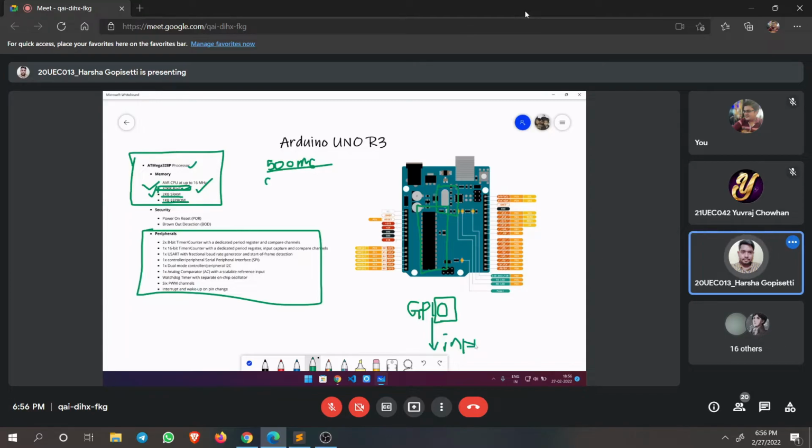You saw the input case in the sonar project, no? There you will be taking the duration. Actually, pulseIn will keep the echo pin high. Whenever the trigger signal comes to the sensor, it goes low. The duration from high to low, the time that the pin is kept high, will be recorded.